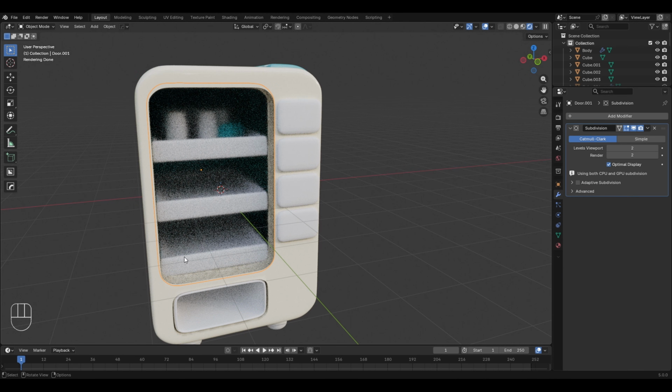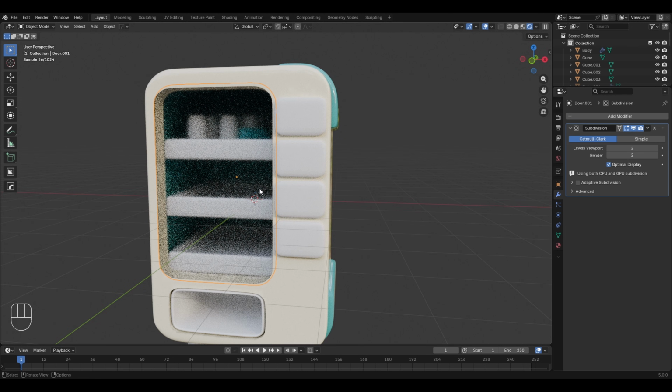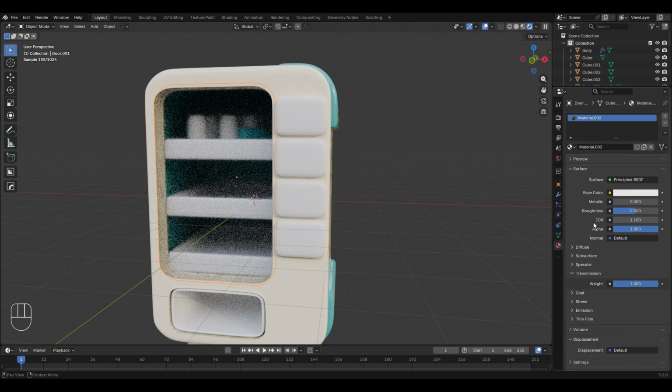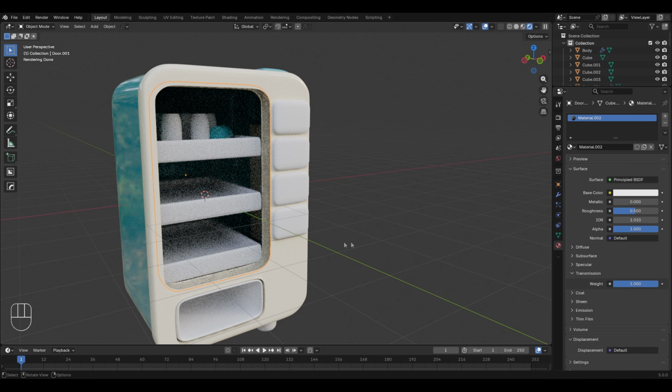and this will give us this empty space where we have the glass now, but currently it's too blurred, which is basically happening because of the index of refraction value. So I think I should lower it down even further. Let's keep this to 1.02, or I'll bring it further down to 1.01, and I think that this one looks better. So I'll keep this one as the final.